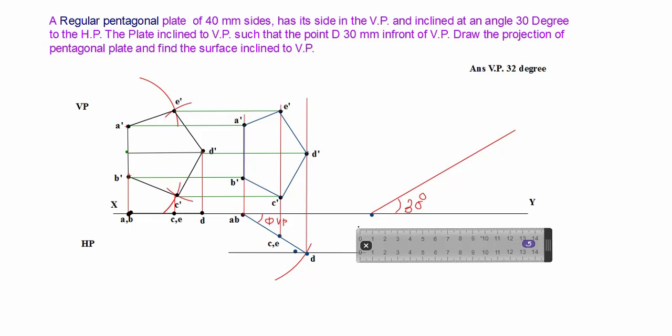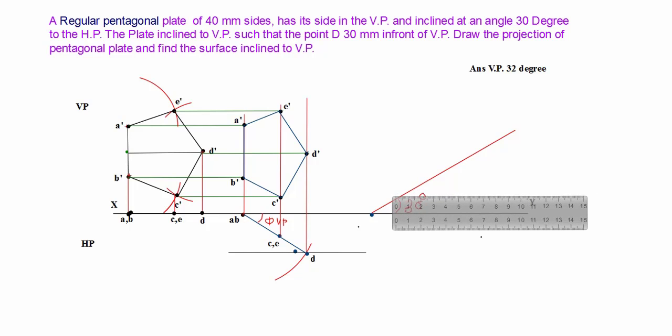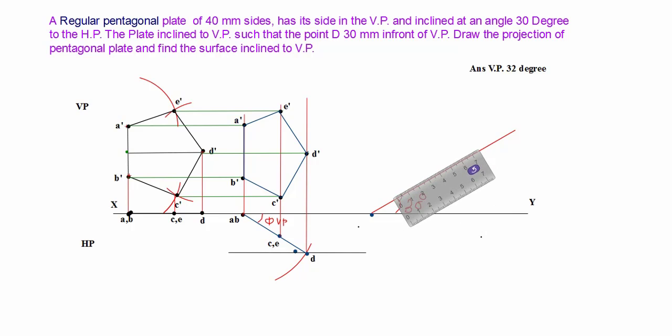Now on this inclination line, the A dash B dash is 40 mm. It is perpendicular to HP. So always the elevation is a true length, true side. Similarly in second stage, it is a true dimension of 40 mm. So first I arrange the scale on inclination line, and we mark the 40 mm distance.